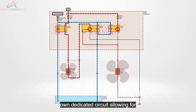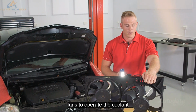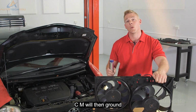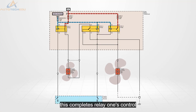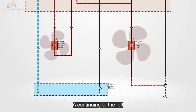Each fan has their own dedicated circuit, allowing for maximum current flow through both motors. For the low speed fans to operate, the coolant must reach a predetermined temperature or the air conditioning is switched on. The ECM will then ground the low speed driver of fan relay 1. This completes relay 1's control circuit, closing the normally open contacts, allowing current to flow to the right side cooling fan. The current will flow to terminal 30 of relay 2, and then 87A, continuing to the left side cooling